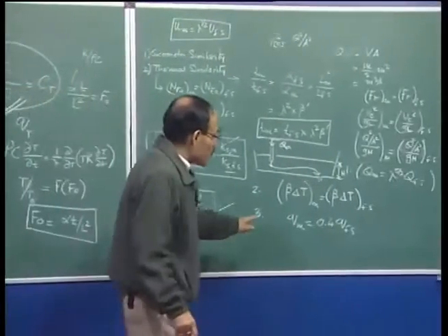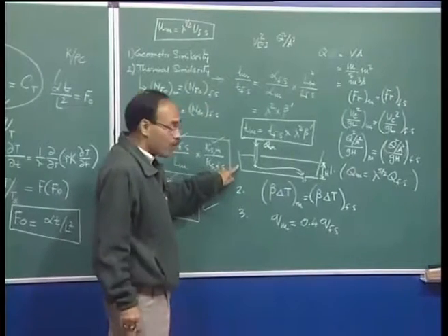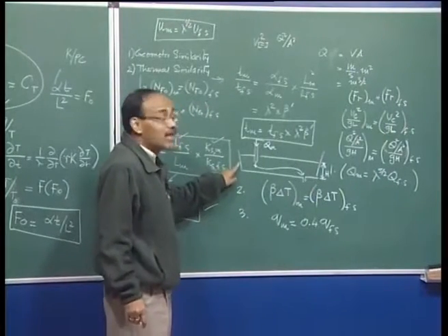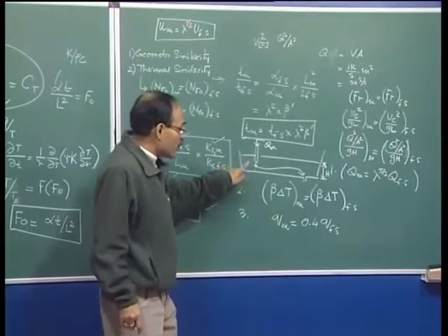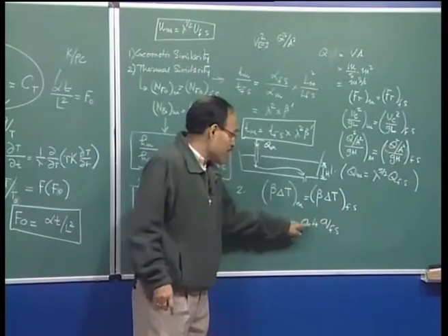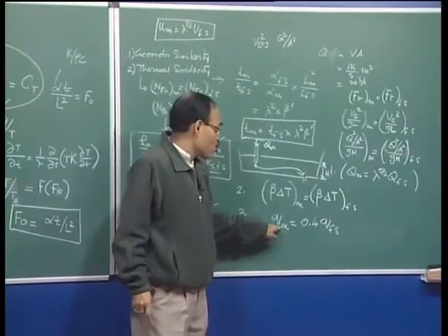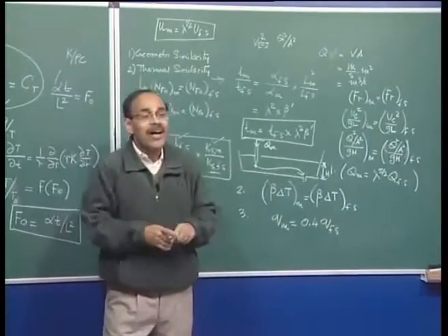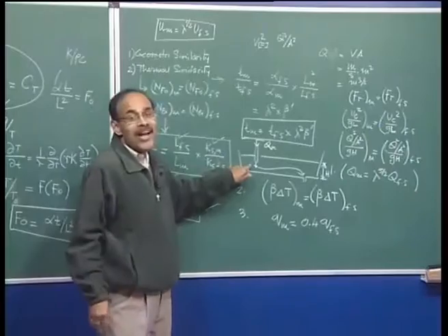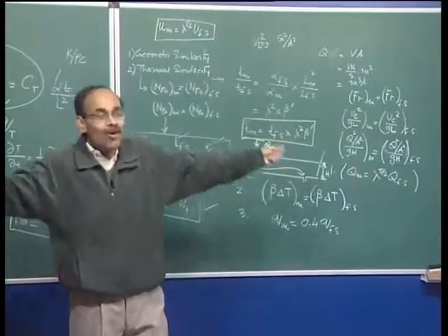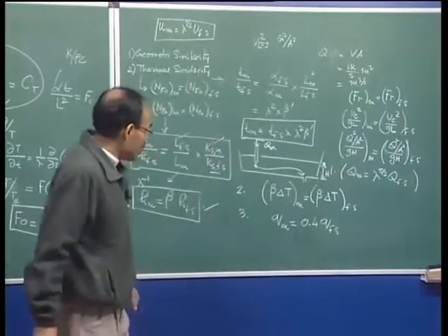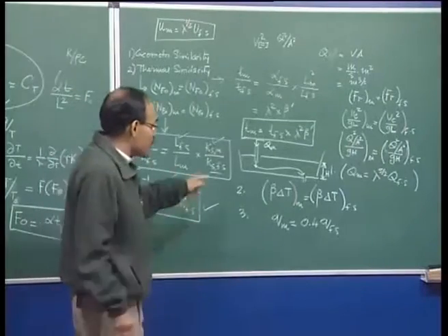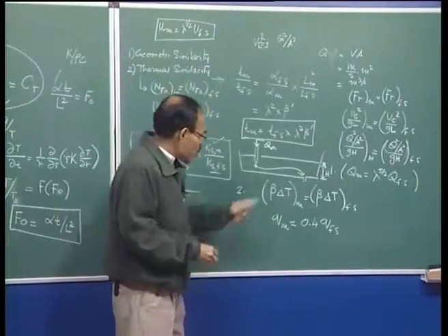Now, as I mentioned, typically in industrial systems we can have 5 to 10 kilowatt per meter square as the heat flux. If it is 10 kilowatt per meter square, then what we require in the model is going to be 4 kilowatt per meter square, and if I have a glass vessel and 100 degree centigrade temperature of water, I cannot get 4 kilowatt going out of the liquid water bath through the glass vessel itself. So, this condition cannot be satisfied.